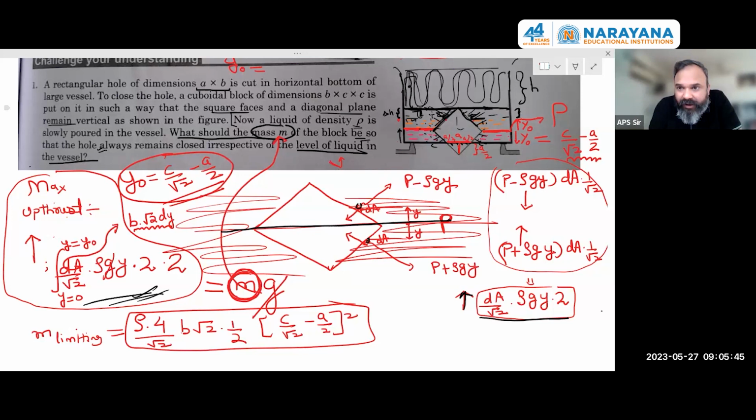Think again what I'm saying. If you keep on filling liquid here, there will be direct pressures here, which will have a downward component. So I'm happy with that. I need not increase my mass. But by virtue of that excess liquid layer that you have kept, pressure will increase everywhere. So my logic is, don't look into the increase everywhere. First, look into the increase at the top surface. That increase is rho g delta h. Delta h can have any value in between. So it's not about this value. It can have any value in between.